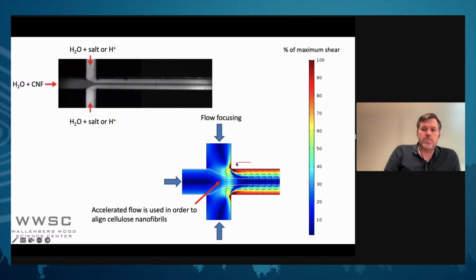In this case, the maximum shear is still found at the walls out here, but here we have no fibers or fibrils. Fibers are only inside. But the elongational flow is the one that creates the strong alignment. And from one perspective, it's not the shear that creates alignment. Shear consists of two different types of deformation: elongational flow and rotation. So the elongational flow that we can set up here is the perfect way of achieving alignment.